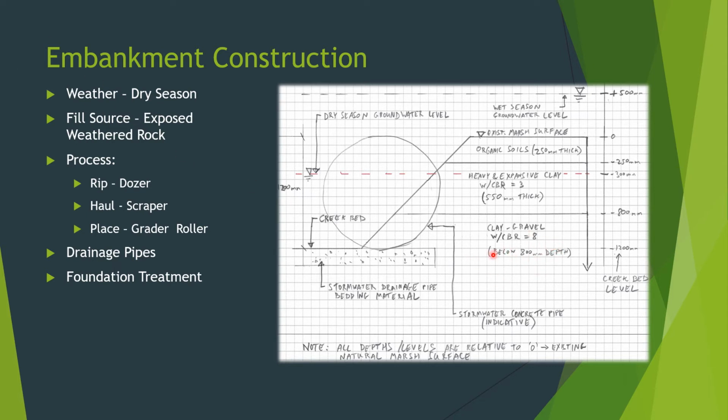This gravel layer appears to be reasonably effective and would be a good founding base for our stormwater pipes, and you can see where they'll be constructed within that layer based on the invert of the pipe matching the current invert of the creek bed.